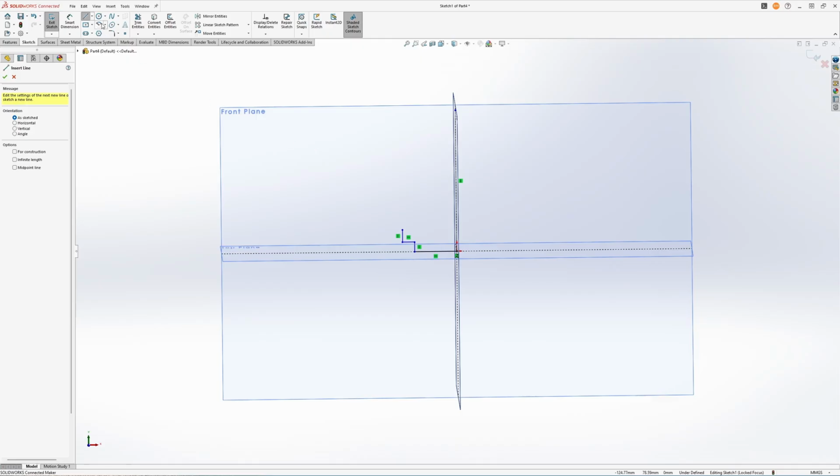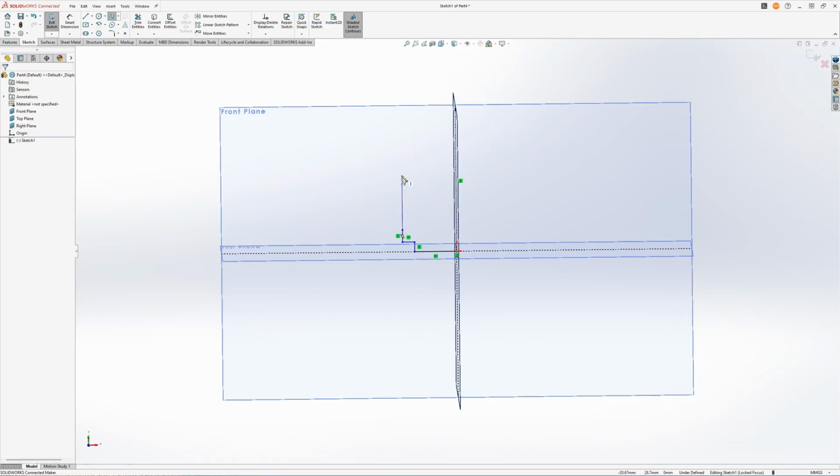And then we will do our dome, and for that we'll use a style spline. So I want it a little bit sharper, so something like this, let's say. Maybe you can start to see it now. You can see this is the cross section of the dome, and as we revolve it, it'll become a complete dome. So let's try to implement some dimensions.